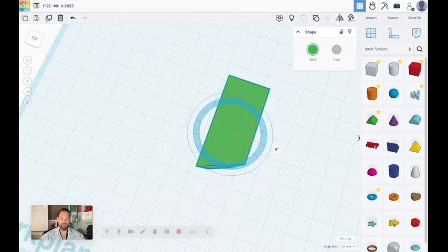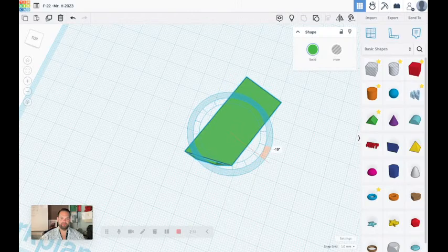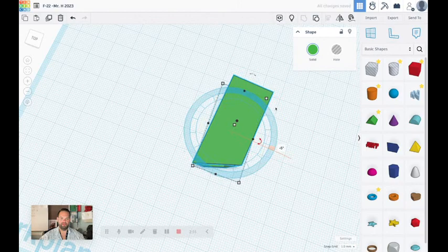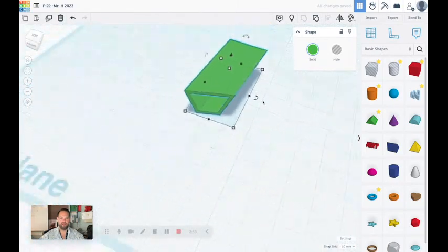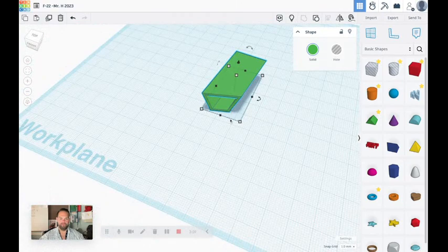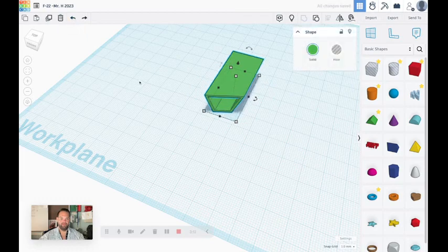So we're going to turn it to -5, but just be aware that if you tilt it to -5 and then you need to make this longer, it could make your object no longer be the same shape. So you want to make it as long as it needs to be first, and then add the -5 degrees. Otherwise, you could end up with some issues.